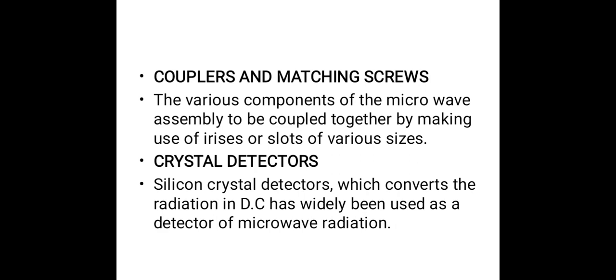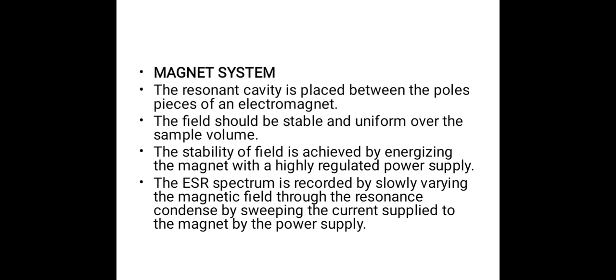Couplers and matching screws. The various components of the microwave assembly are coupled together by making use of irises or slots of various sizes. Crystal detectors. Silicon crystal detectors, which convert the radiation to DC, have widely been used as detectors of microwave radiation. Magnet system.